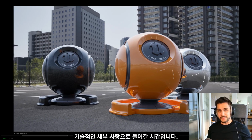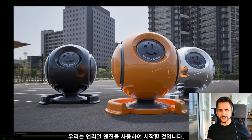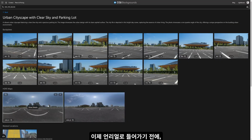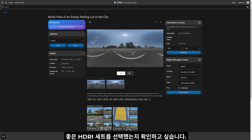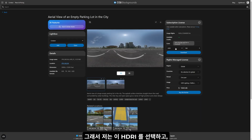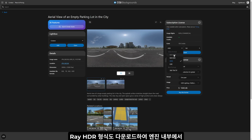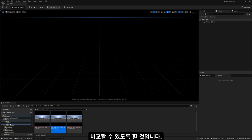Time to dive into some technical details, and we're going to start off using Unreal Engine. Now, before we jump into Unreal, I want to make sure that I select a good set of HDRIs. So I'm going to be picking this one, and I'm going to download this in the traditional HDR format, as well as a 16K resolution. Additionally, I will be downloading the RAY HDR format so we can make comparisons inside the engine.